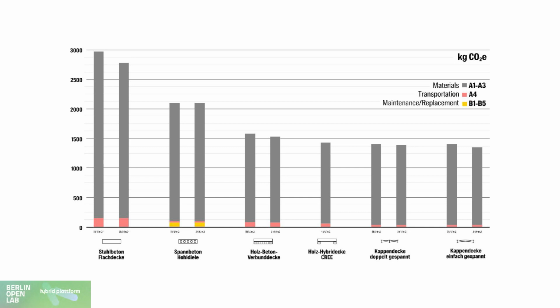So the more mass you have, the more sound insulation you have. That's why buildings are becoming heavier and heavier as regulation on sound insulation is going up. And that's a problem of timber construction, because timber is very light. So what you do in the end is you pour concrete on top to make it heavier, and that is probably not such a good idea in this regard.